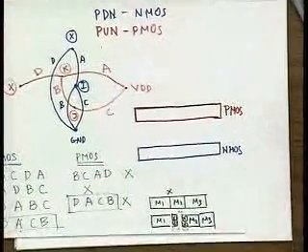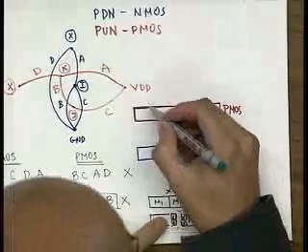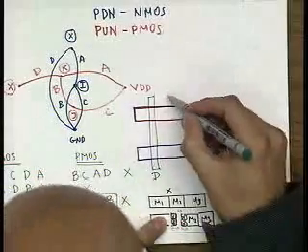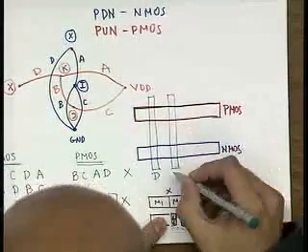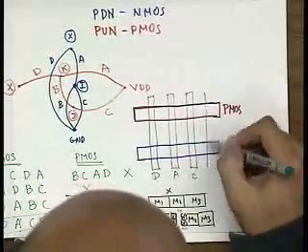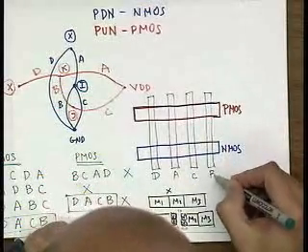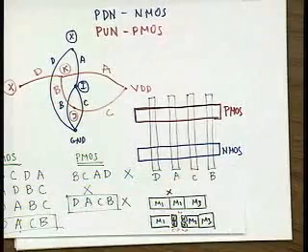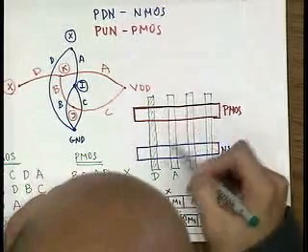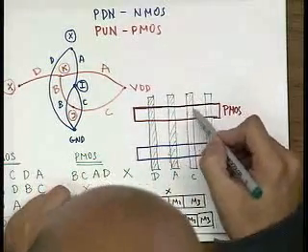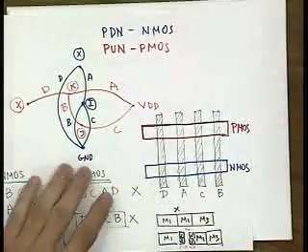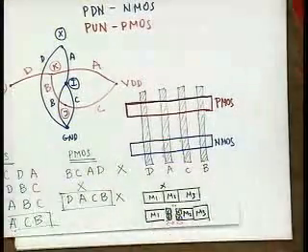So now what I know is I can do these diffusion strips, and then I do D, A, C, B. So if this is my diffusion that corresponds to D, then I have A, C, and B. So now we can figure out also the nodes that correspond to these diffusion lines and the sharing of source and drain regions. So that's the layout.